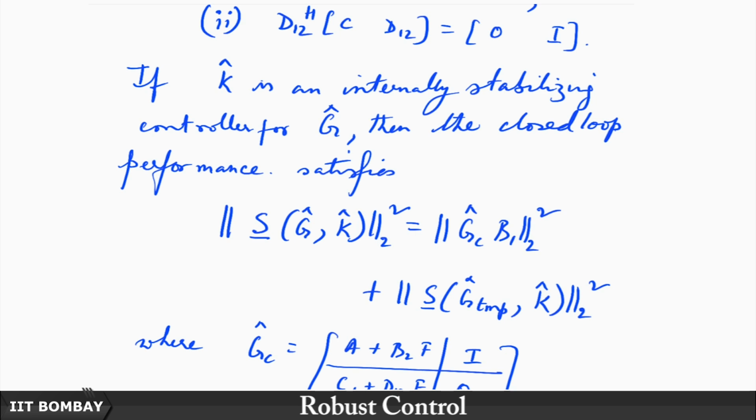It is basically the star product, that means you have the usual connection block, the W coming in and the Z coming out, those are the exogenous signal and the output signal Z, and then the Y is fed back through the controller and that spits out U, which is fed back to the plant. So, it is a typical plant controller combination, and the star product is what we had called it. Again, revisit when we defined this as a star product 2-3 lectures back.